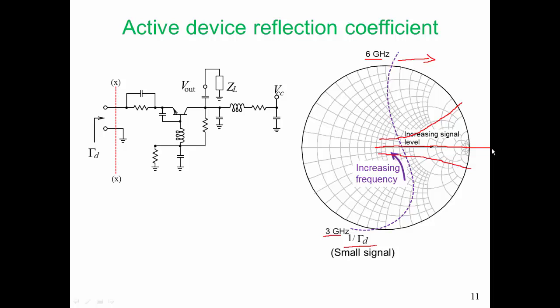In a simple reflection oscillator design, we would try and follow that line where BD is equal to 0 and the frequency of oscillation is solely determined by the resonator network. But at RF and microwave frequencies, the parasitics associated with our transistors are really quite large, and so we cannot ignore them. In addition, in this design, the inductor in the base results in an inductance being presented to our resonator network.